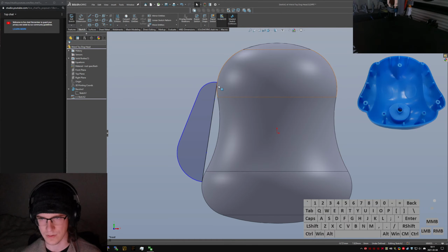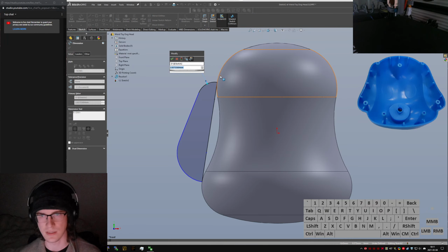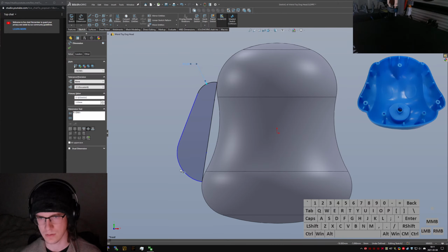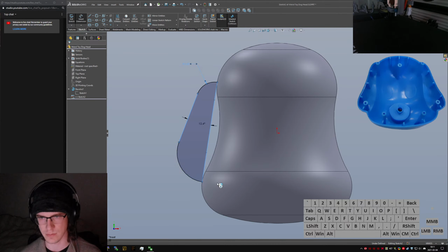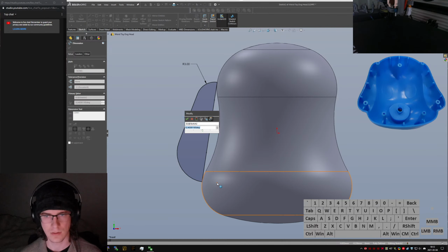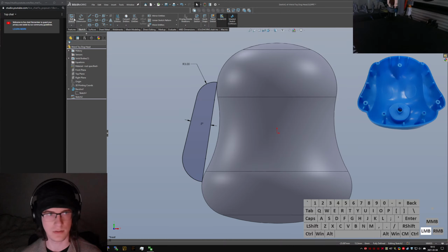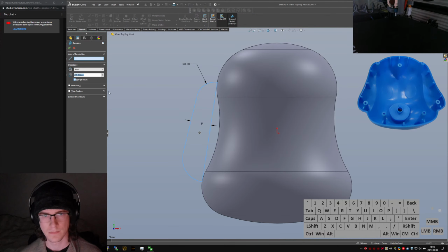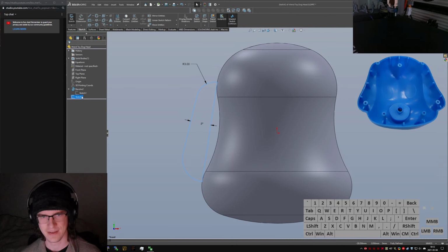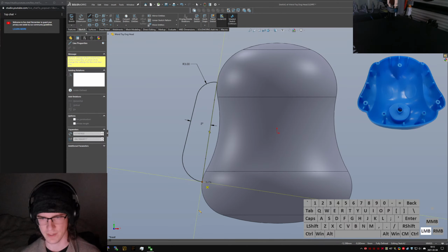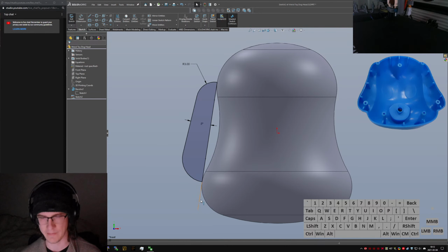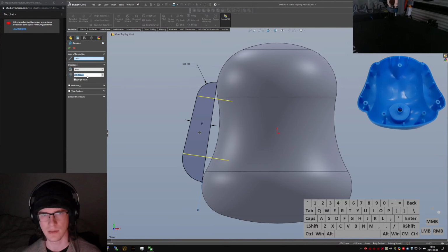Okay, I'm pretty sure this one can't go anywhere, so now I just have to define these radii. I'm going to say that this is 3, and then use an angle to define this one. It's only like 5 degrees, it's really not that much. I know I said I was going to be using surfaces a lot for this. It appears that I lied, and that revolving things is way easier. Oh, hang on. I forgot to add a line. Having a construction line in there, if you have just one, then the revolve tool will automatically assume that it is the thing you want to revolve around.